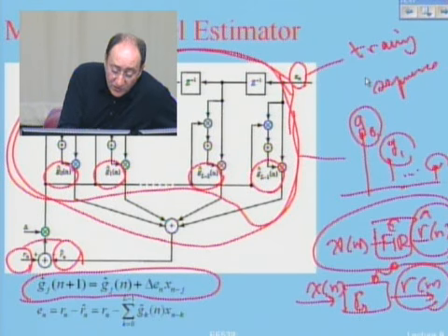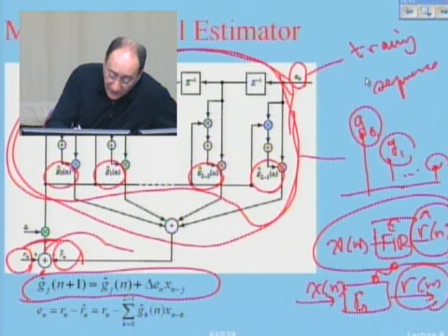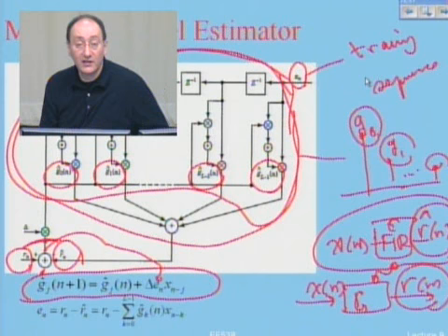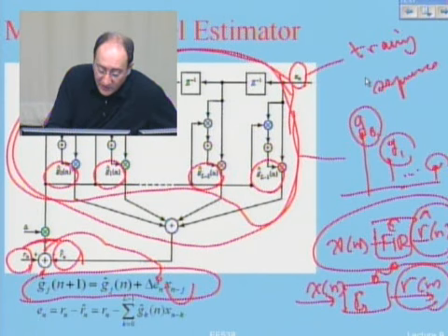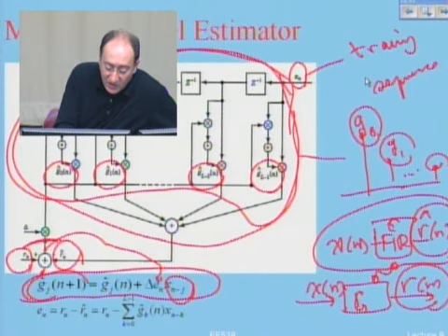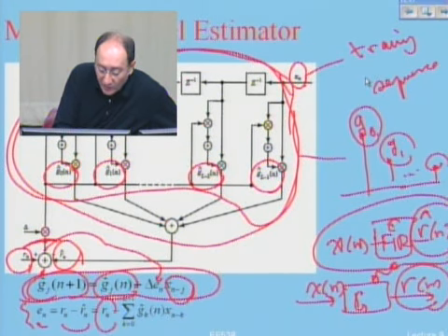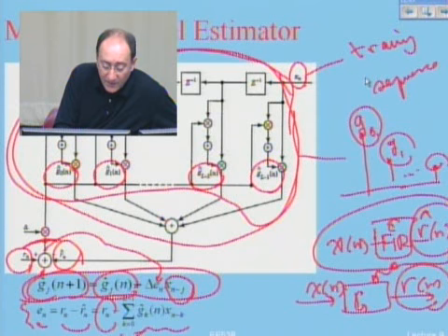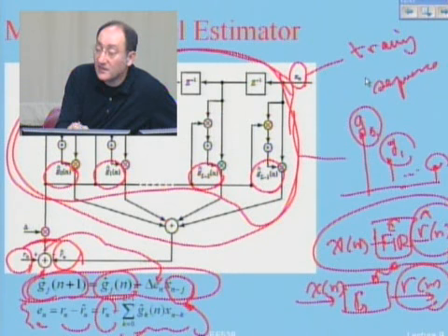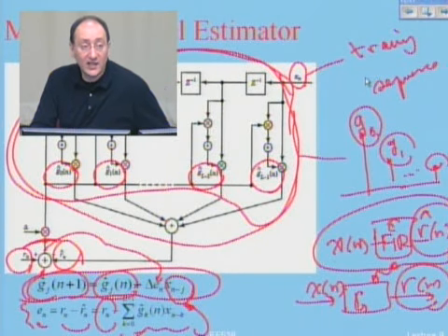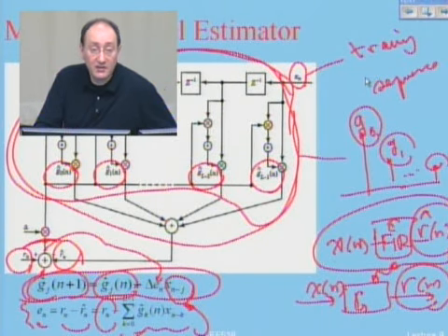The difference between these two is my error function. I multiply it with this, and then I adjust the taps. So with this simple algorithm, this is my error, the received signal minus the estimated received signal. I put it inside here, and these taps adjust themselves. Delta is a very small parameter.